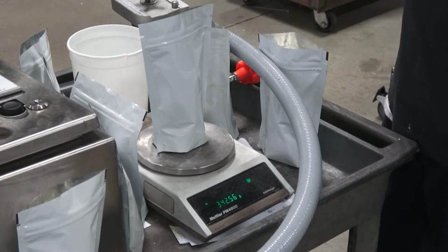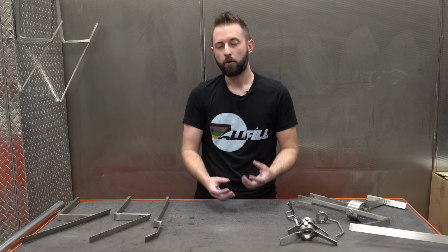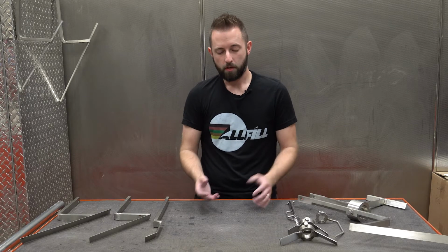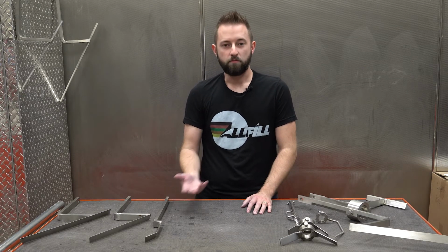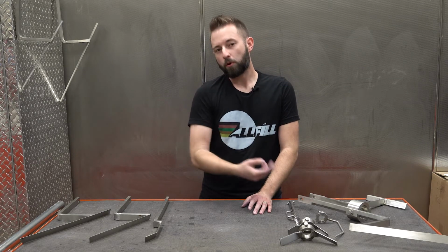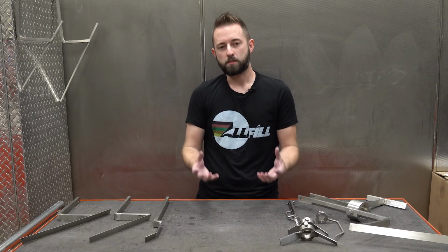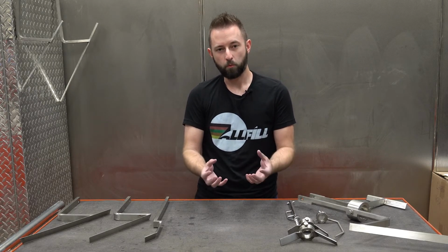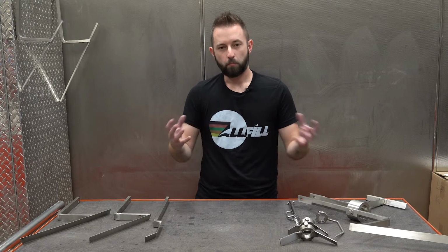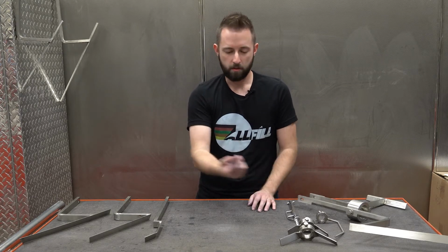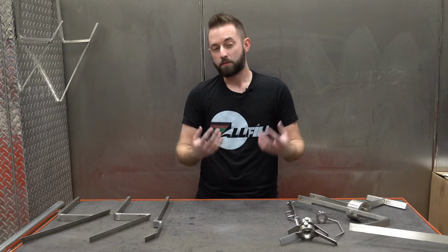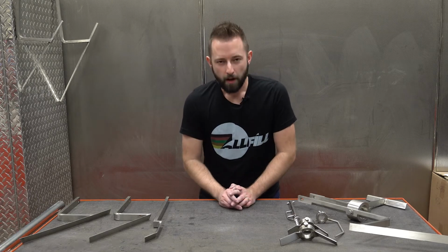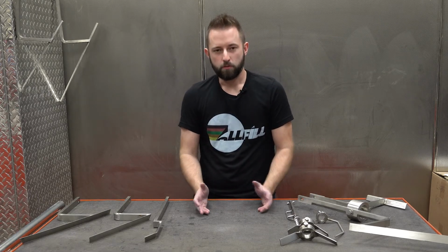Varying amounts of grams per revolution are coming out of the auger, which can cause massive fluctuations. So continuous agitation can be very, very helpful in keeping the product moving and keeping it in a consistent, homogeneous state. It never has time to settle and become more dense or become overly fluid because it's a continuous motion at the same rate.